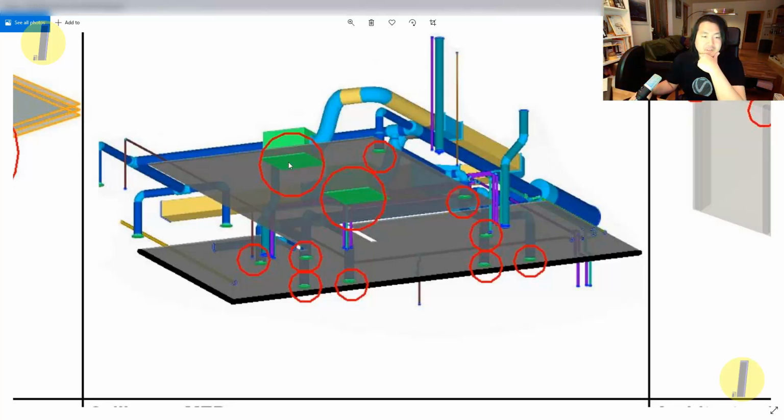So if certain exhaust duct systems collide with the ceiling area, you can make an opening, or report it as a collision, or if small pipes come through the ceiling area, you can accept them also from the collisions report.